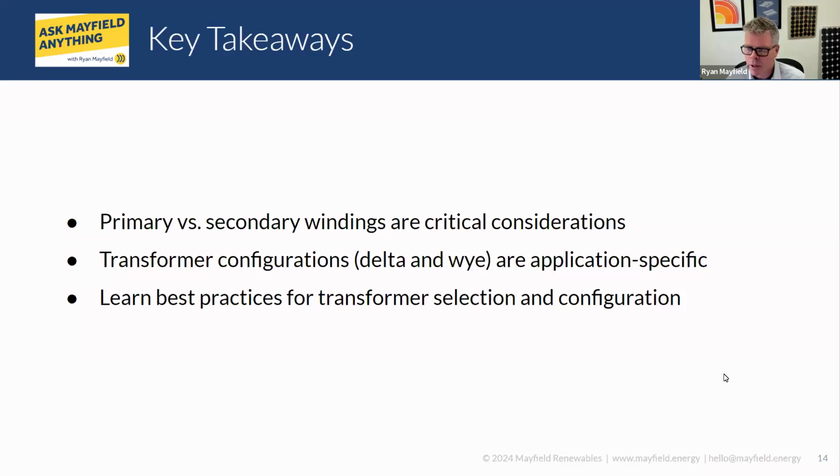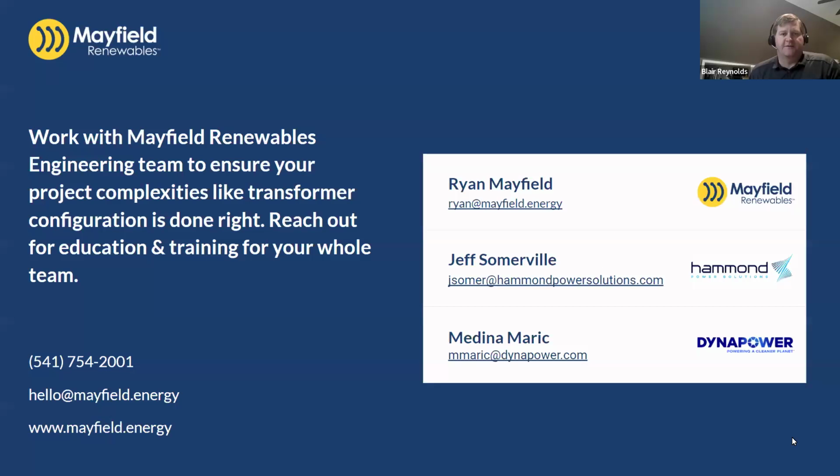Perfect. But these transformers are rated for continuous duty, right? Yeah, exactly. They can do 100% continuous if needed. Yep. Cool. And going back to our prep calls, I think that's one of the things that, when we're doing all of our electrical calculations, we've gotten so used to a 25% safety factor on just about everything. I think people maybe start to apply that to the transformers as well.